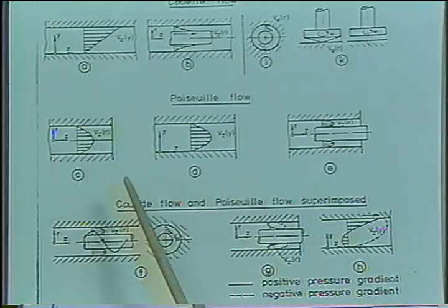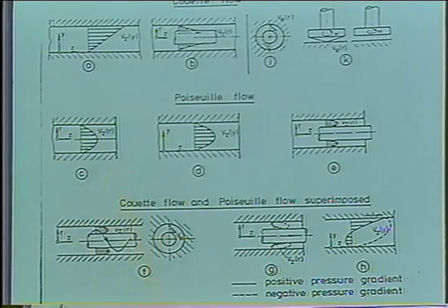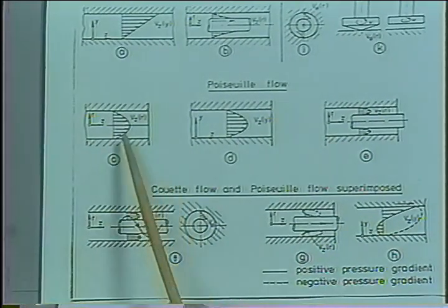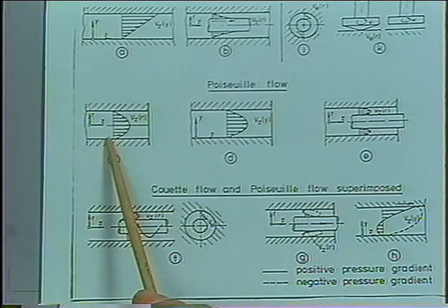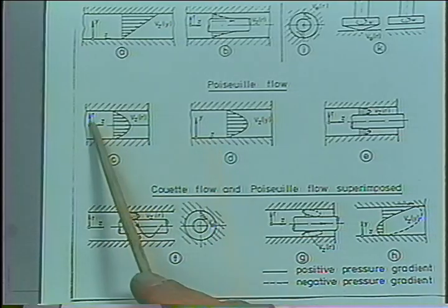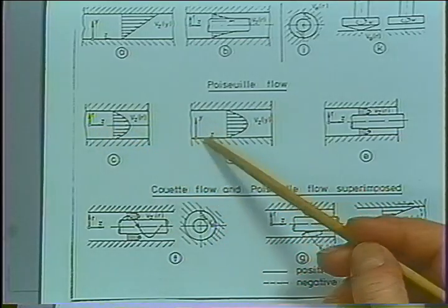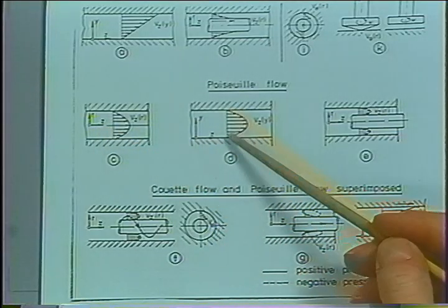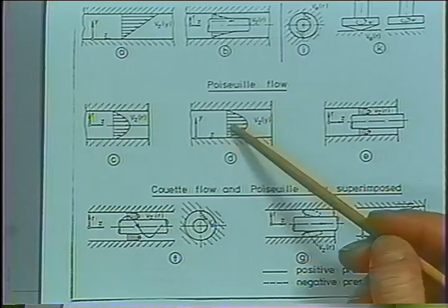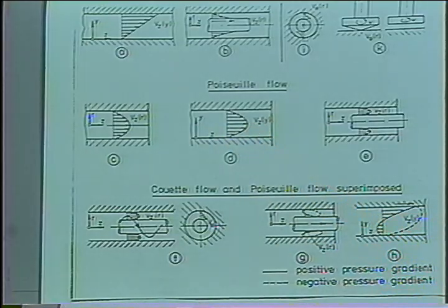Shear flow might also be generated by pressure flow in a pipe or in a slit. Here, pipe, you have axisymmetric. That's why I put the coordinate system in the center. Here, it's a slit which has stationary walls, and the flow is just due to a pressure gradient.